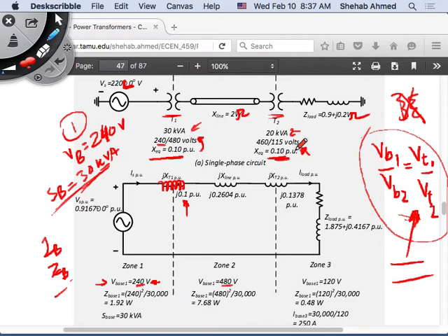Yes, sir. So you said the transformer is represented by the impedance, just that? Yeah, all our transformers, if you're given an equivalent series impedance for the transformer, we will convert them to either a short circuit or an impedance in series. So the transformer is either going to be represented as a pure short circuit like this, or as an impedance in series. So you choose the same impedance as given because the ratio was the same?